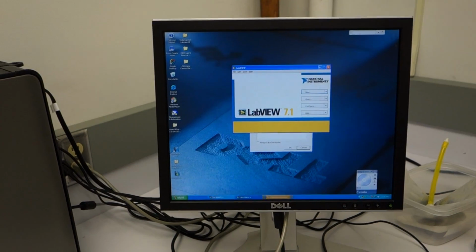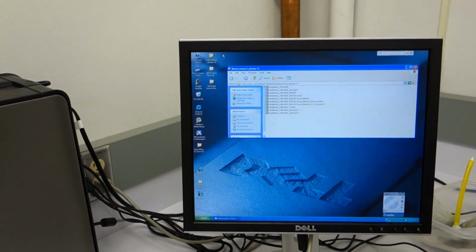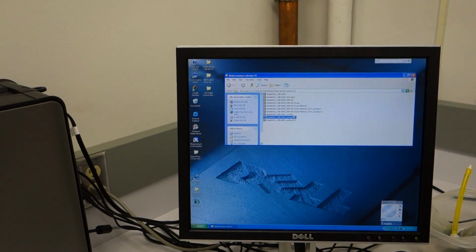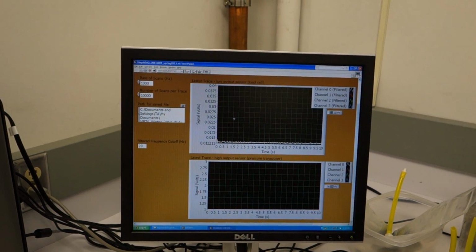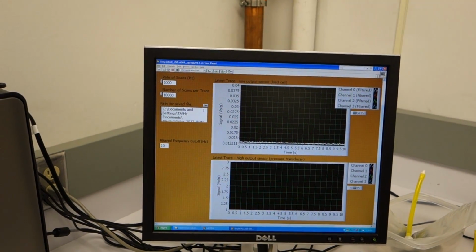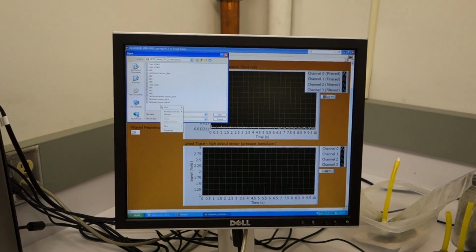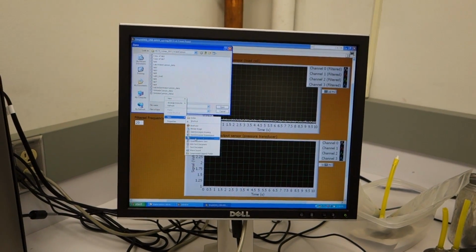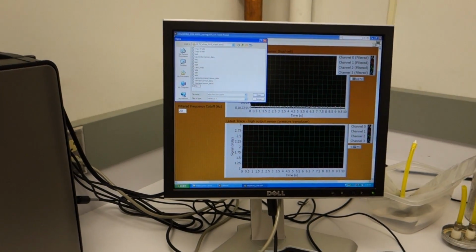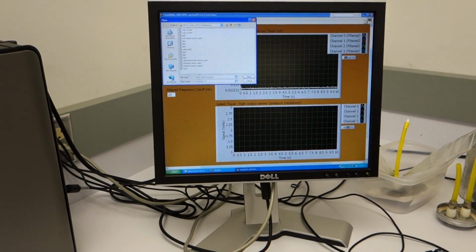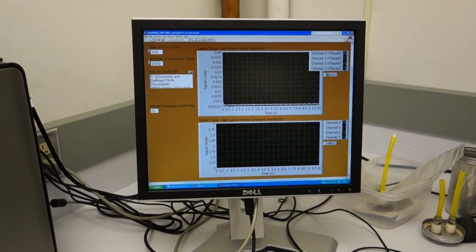So right now I've opened up what I've done to get here. I'll close out to show you. We have a folder, Water Cannon LabVIEW VI. Any of these files will work. I'm working on Spring 2013 right now, and I want to save my data so I can plot it later. So I'll navigate to a window where I want to save my data, and I need to actually create a text file first. So new text document, I'll call it test1, and then we need to select it and open it. Now that data will be saved to the text file, which we labeled test.